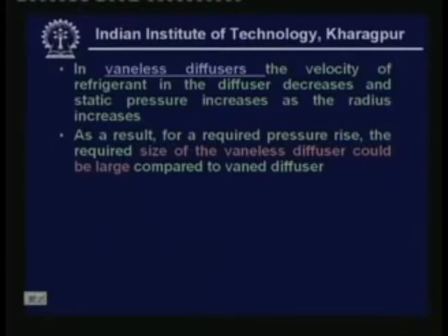Since for a given pressure rise, or for a given drop in velocity, you require a larger diameter if you are using a vaneless diffuser, the size of the compressor using a vaneless diffuser will be larger compared to a vaned diffuser compressor.